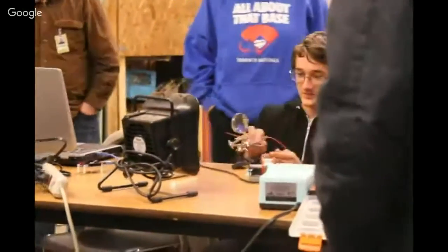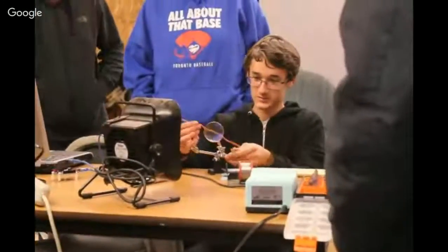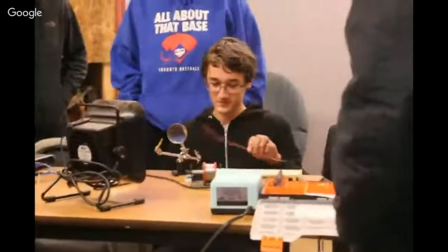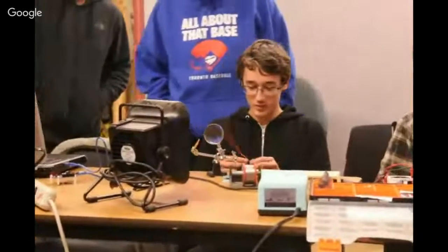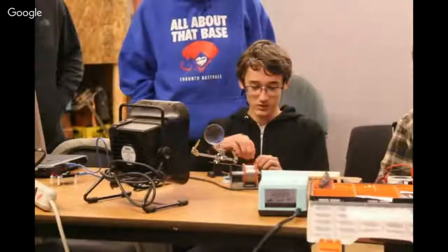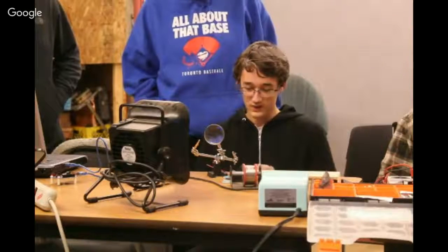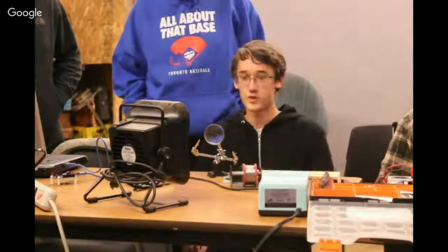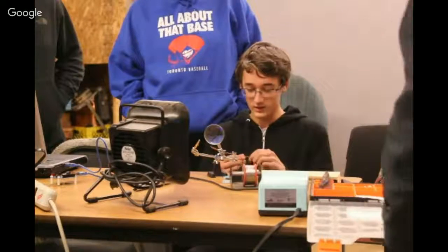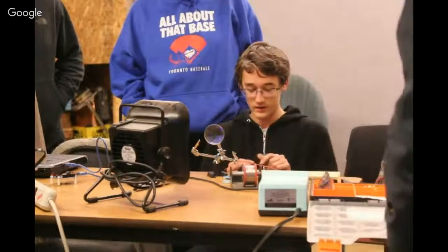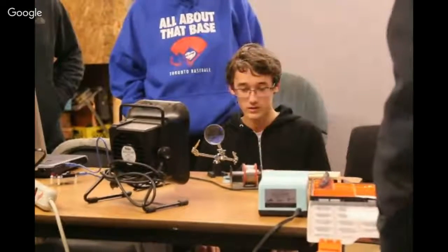So there it is. Why do you like it better now than you did before? A minute ago, the wires weren't actually touching, there was a gap of solder in between them, so it was a pretty neat trick. And if the solder cools too rapidly, it's called a cold joint, so it's a lot weaker, and you can tell if the joint is not very shiny. It's like a dull crystal.